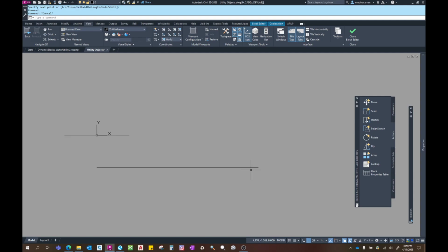Then I can add a vertex, turn off my ortho snaps, turn on my polar tracking. In this circumstance, I want the 30, 60, 90. So this is 30 degrees as shown next to my cursor. That's 60, and I will just type 1.5. Perfect. Now I have it angled at a 60 degree.